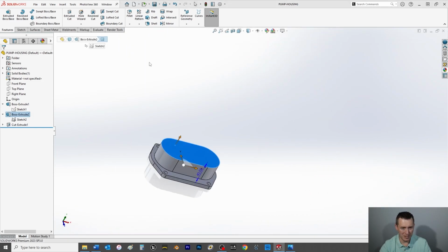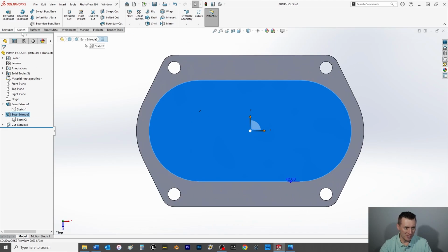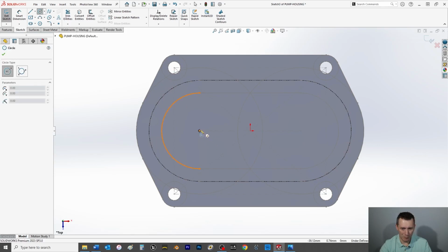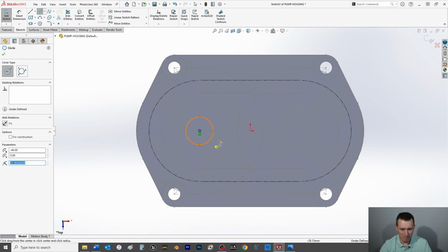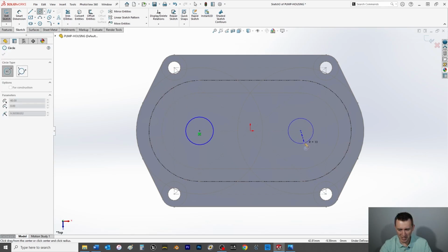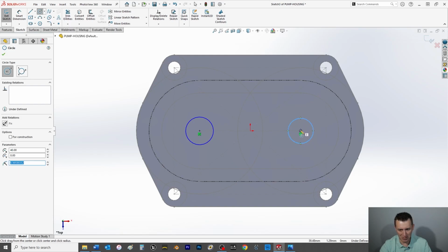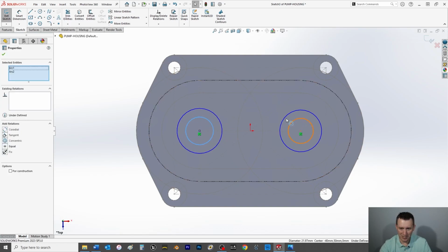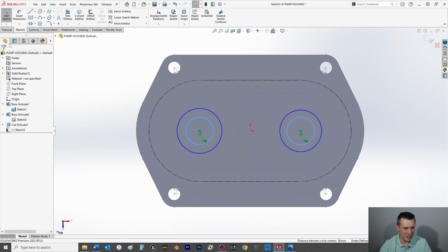Now I'm going to come up here, choose this plane, choose a sketch. I want to bring my master sketch back for this because I want to use this reference line here. And we're going to create our extrusions. One of them is basically a housing for the bearing / rod axle, that gear. So for this is an internal cut. We want these to be equal.